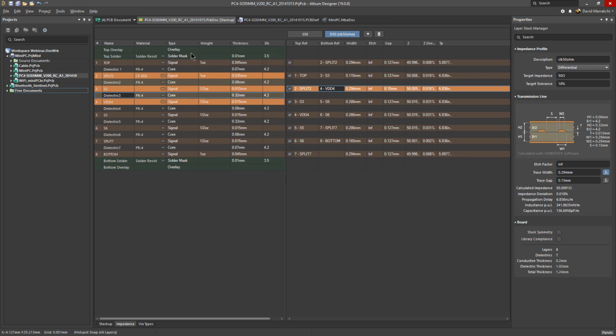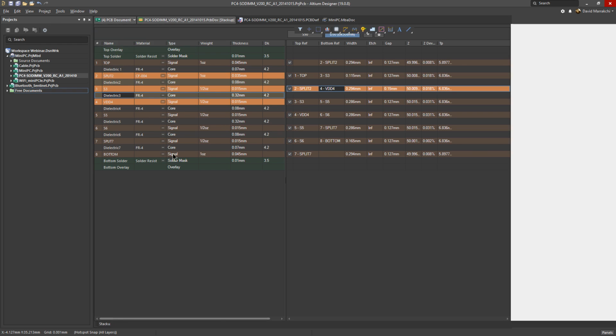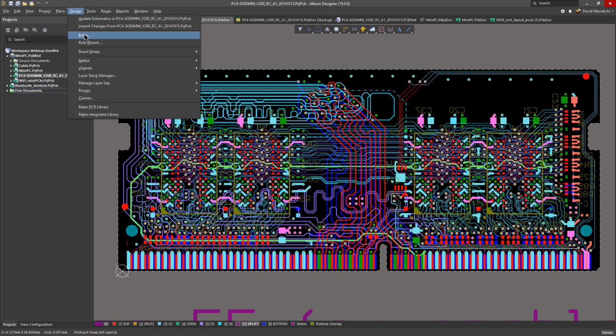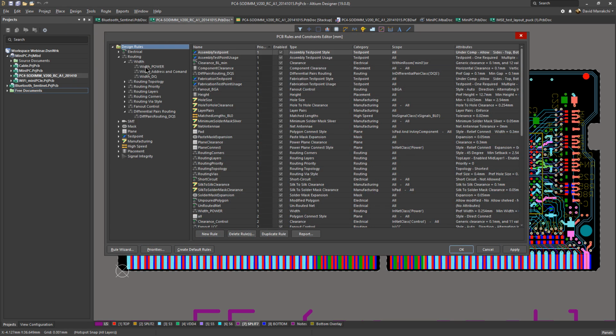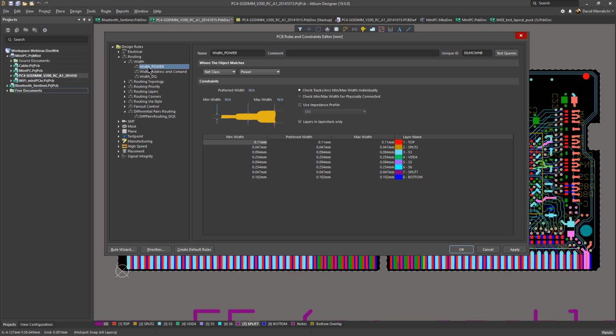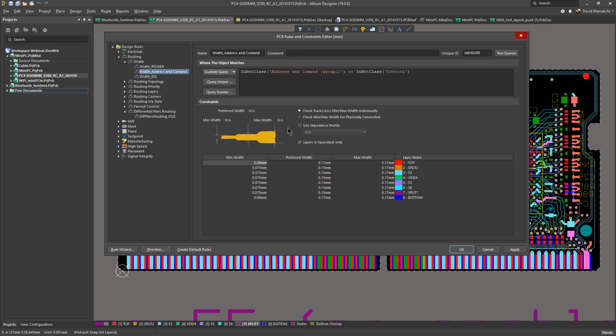So you need to save your file, and then we can go to our PCB editor and then access our rules. Through the routing rules, we can access all those impedance profiles. So for example here, if I want to use this particular profile for the single line, I can just check this right here, and then you can see everything changed accordingly. So I have my minimum width for every layer, and you can see it's different, and all of these are corresponding to making sure that my impedance is controlled within 50 ohm and within the tolerance.